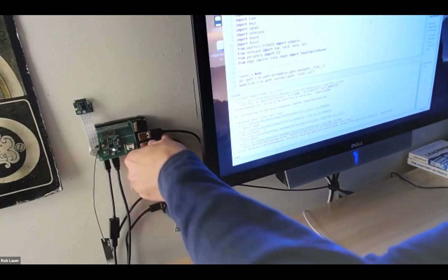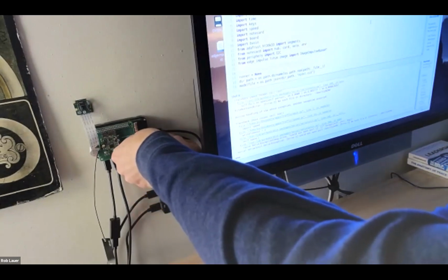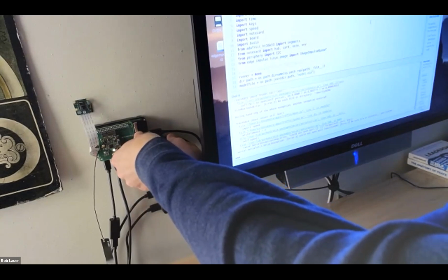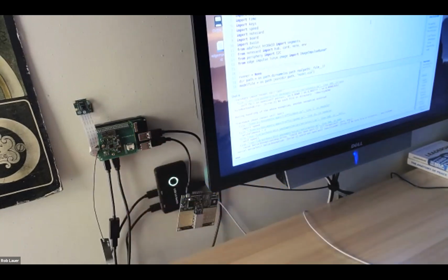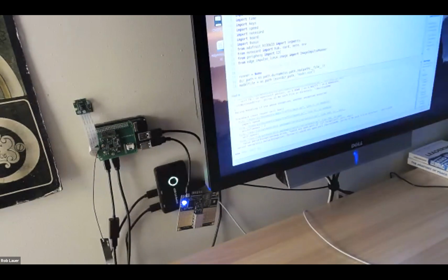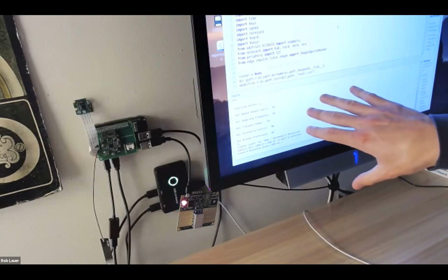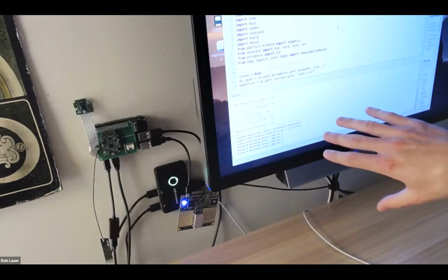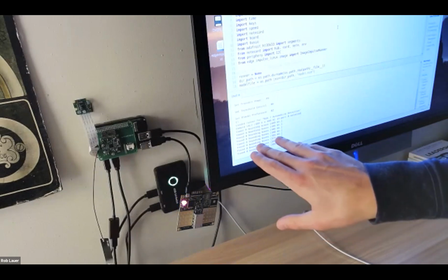So what I'm going to do, usually this means there's an issue with the serial interface. So I just have to unplug that radar module and plug it back in and hope for the best. Let's run that again. Okay, so we're setting some of those configurations on the Doppler radar sensor. Hopefully you can read this, but probably not.